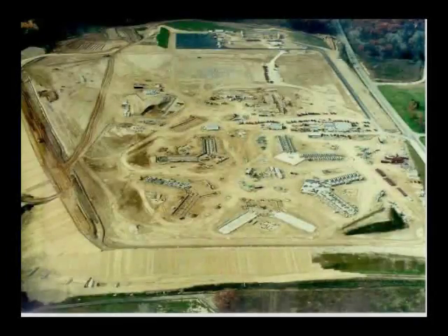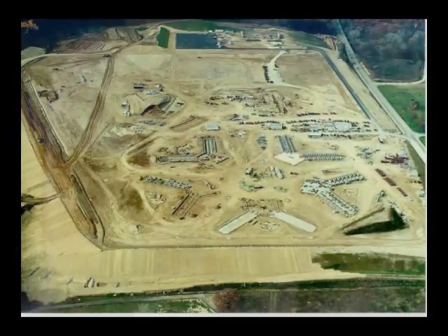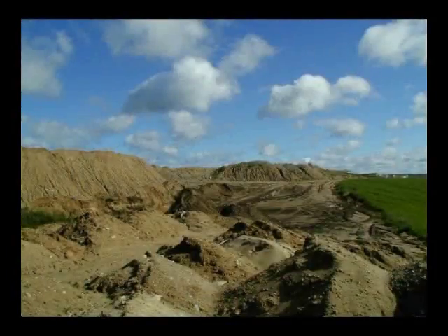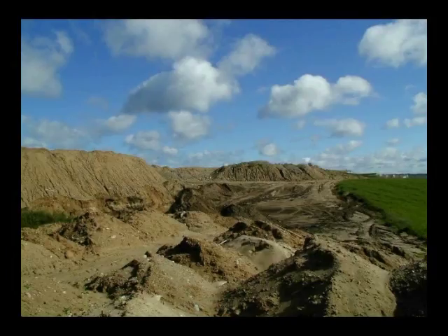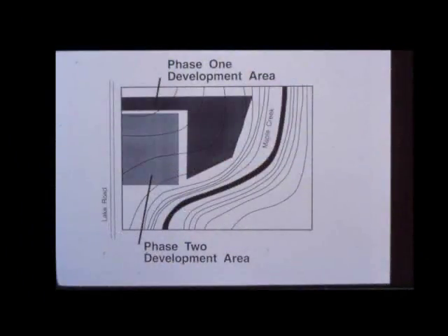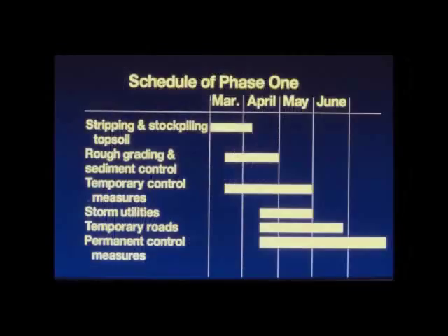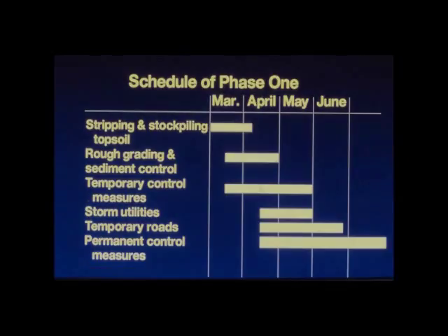Phasing or staging is an erosion control practice that needs to be considered during the planning process. Plan the stages or phases of development so that only areas which are actively under construction have bare or disturbed soils. By working in small sections of the project and then stabilizing the section prior to disturbing a second section, it is possible to limit the amount of earth disturbance. As an inspector, you should verify that the project is proceeding according to the plan and that each section of work starts only as the previous section is stabilized.